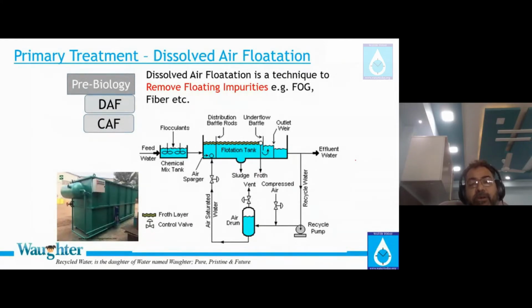Now, some people do not like me when I say that, but a typical sewage treatment plant will not use DAF. But in some special sewage treatment plants, we will use DAF. So DAF is in my course. Where will it be used? For example, if somebody says, sir, I do not want microbiology, I still want a sewage treatment plant for gardening purpose.